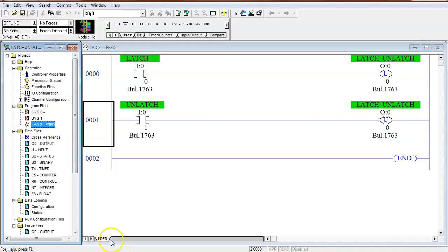That really becomes important when we start dealing with subroutines in PLC 2. In most real big programs, it gets very, very cumbersome to work with them. So what they'll do is take that program and split it up into individual modules we call subroutines. We might have one subroutine that does this and one subroutine that does that. Now instead of me trying to figure out where it's at in 100 lines of code, I can just go to the subroutine that takes care of that thing.